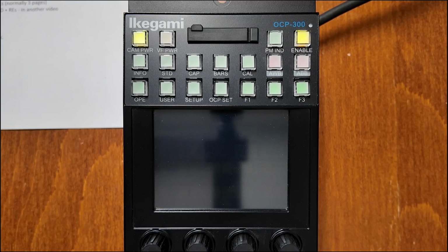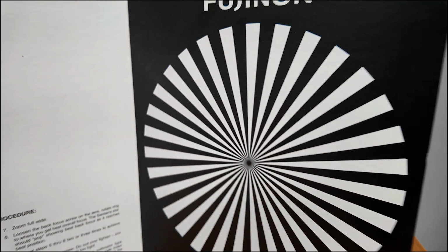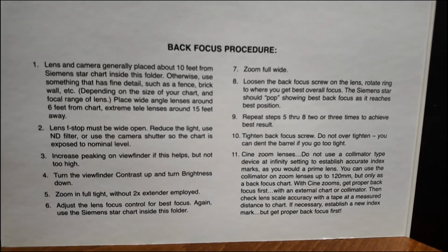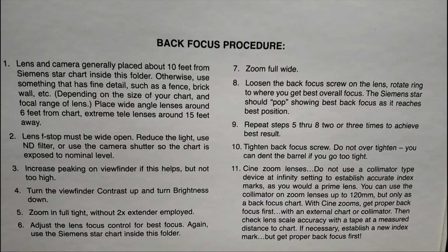Now, if it's the first time that you're working with these cameras, maybe you've just been hired to set up these cameras. That being the case, of course, we probably do the traditional back focus on the lens, especially if the lenses have been reassigned to different cameras. That follows the standard procedure of checking the back focus. Iris fully open for that is always recommended, as you know.